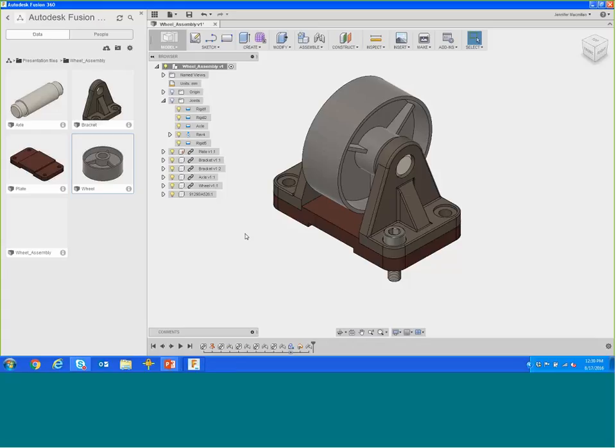I personally find that I like to go to that McMaster-Carr library outside, just going through Windows Explorer and navigating there, then downloading all the files locally and uploading them to my Autodesk Fusion 360 account. If you're constantly using the same fasteners, it definitely saves a lot of time. You can create that library of the fasteners you use on your Autodesk 360 account, and just go to them and insert them as you need them. It saves a little bit of navigation as you're designing.